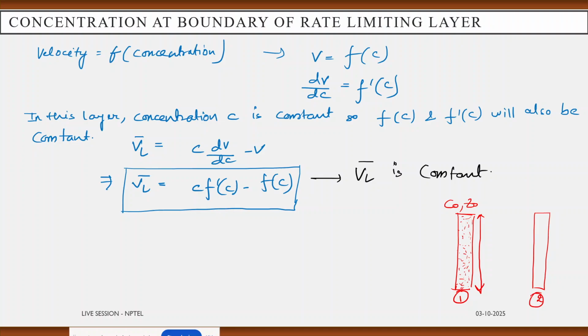In case 2, when it has settled down, there is an interface and this kind of concentration layer, with layer height ZL and concentration CL, and the velocity of settling of solids from this layer is V plus VL bar, where VL bar is the rising velocity.